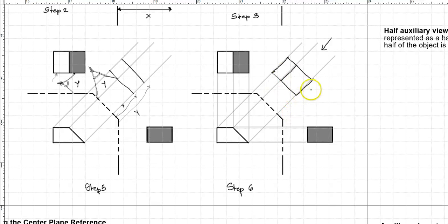So now in here, which is the true surface and what happened to this surface right here? So if you see, the true size is going to be just this surface. Why? Because it's first of all perpendicular to it, and this is our auxiliary view. This is what we really wanted. But when I'm looking in that direction right there, I'm even seeing part of the top surface.